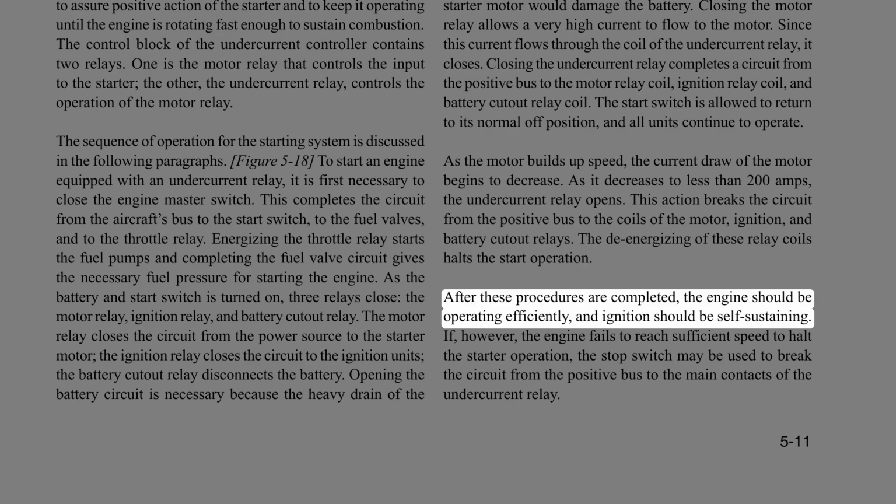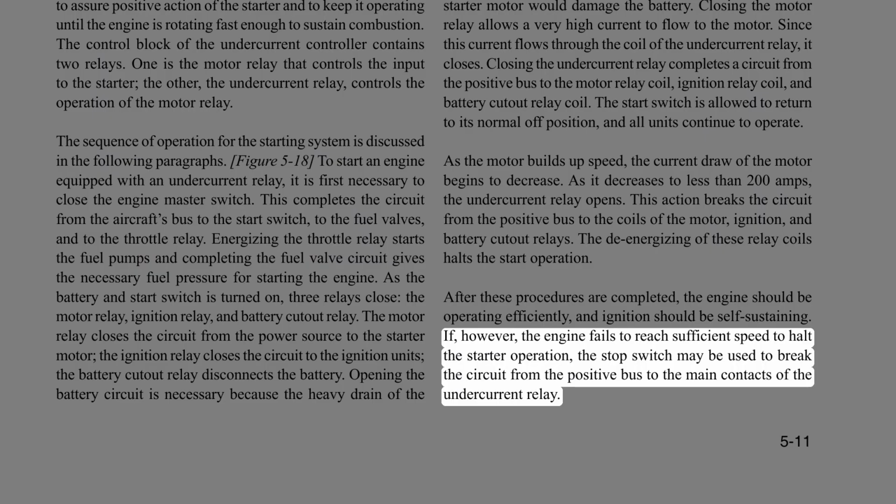After these procedures are completed, the engine should be operating efficiently, and ignition should be self-sustaining. If, however, the engine fails to reach sufficient speed to halt the starter operation, the stop switch may be used to break the circuit from the positive bus to the main contacts of the undercurrent relay.